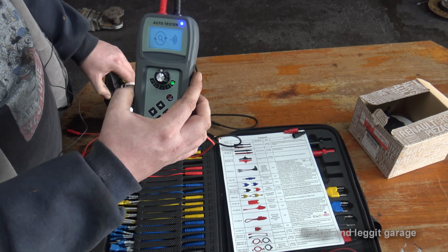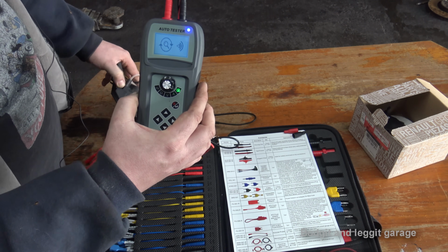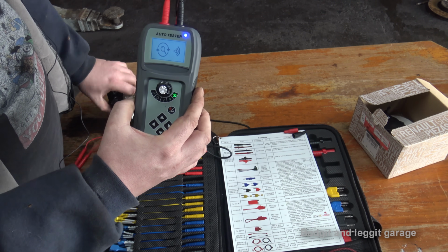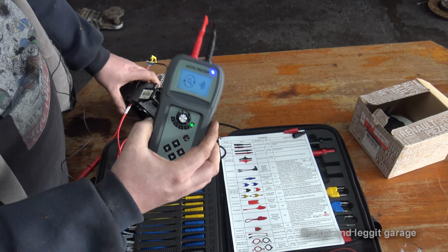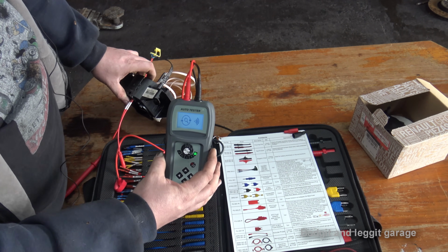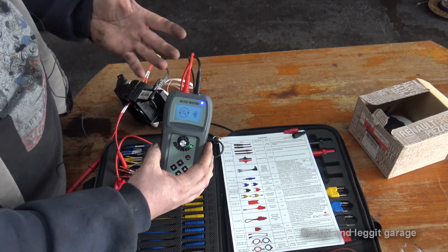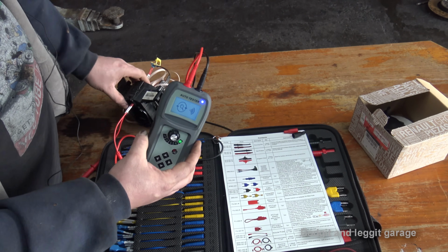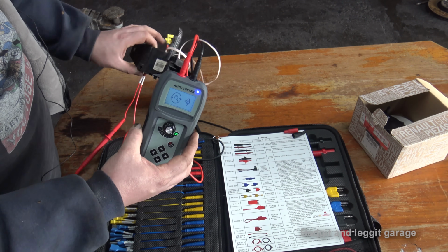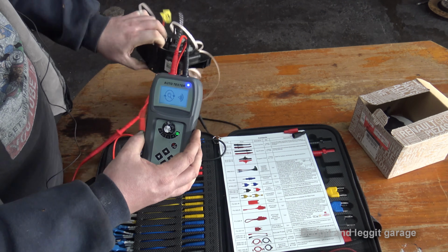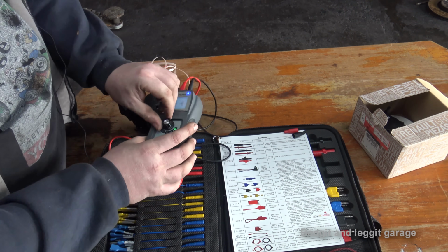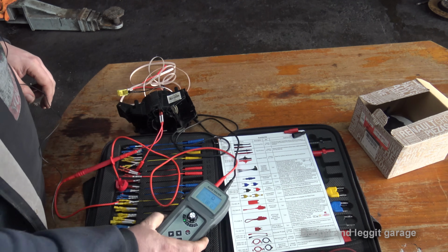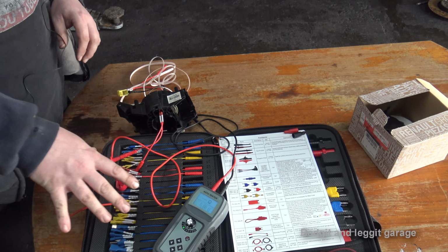Now if the wire is completely and utterly broke, if I can get this to stop, for example, not going to do it now. Now there, then you're okay. But as you can see, this bleeps. So if you were to test this particular one with a continuity test, you're going to think, oh, that's okay, it's making a noise. But it depends how you grab it. And now it's not, yeah, it's flicking. So that's where a continuity tester can put you in the wrong places. Why I don't particularly like continuity testers. An ohms tester is a lot better.